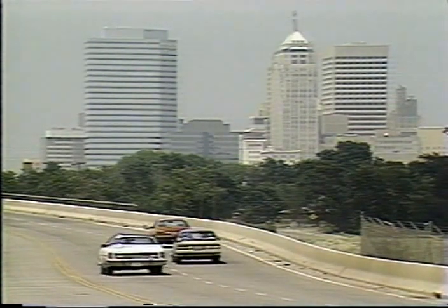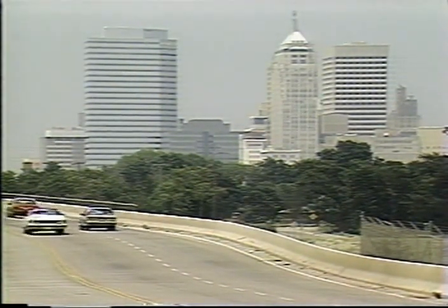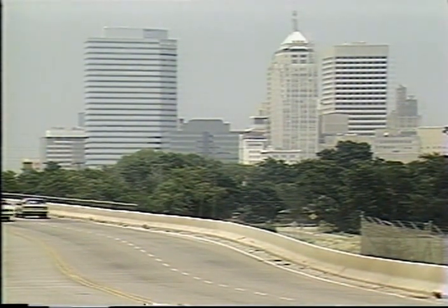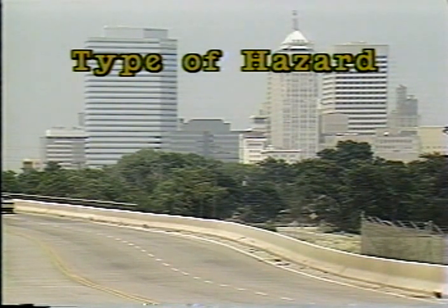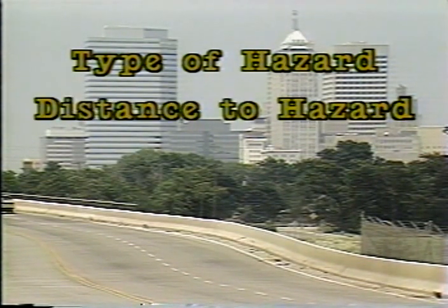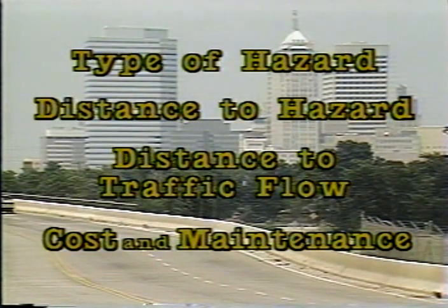Traffic barrier selection, meaning the choosing of one particular system to meet a specific safety need at a certain location, depends on 4 things. 1, the type of hazard requiring a barrier. 2, the distance from the barriers to the hazard. 3, the distance from the barrier to the flow of traffic. And 4, the cost and required maintenance of the system.